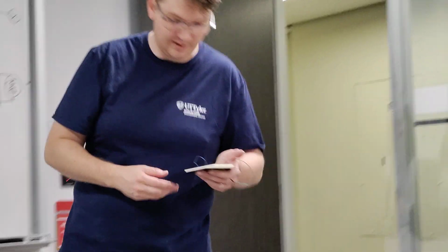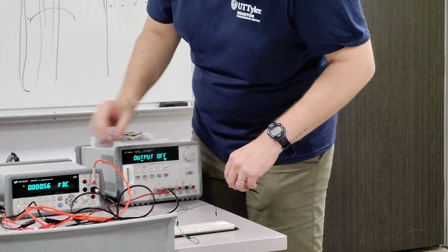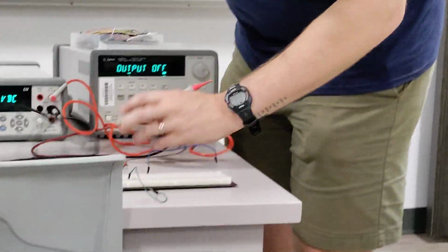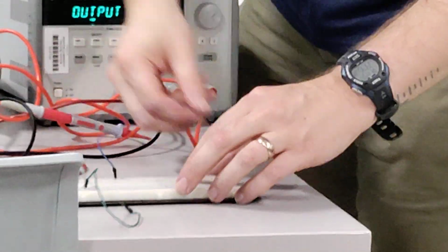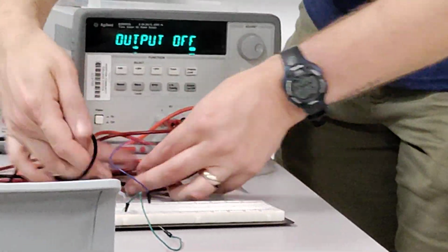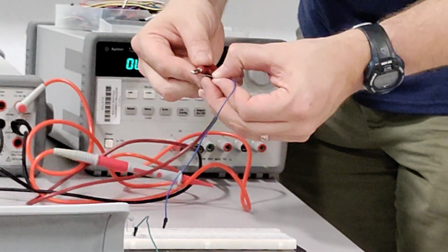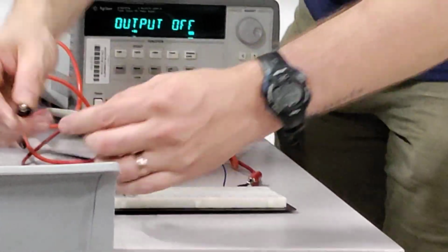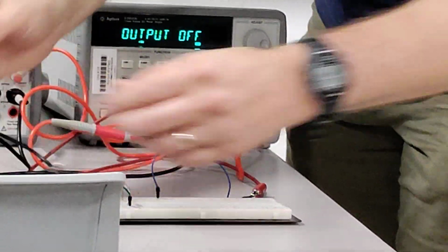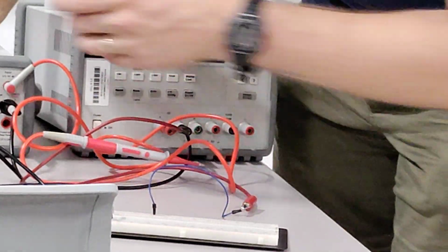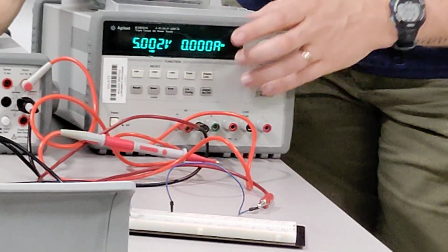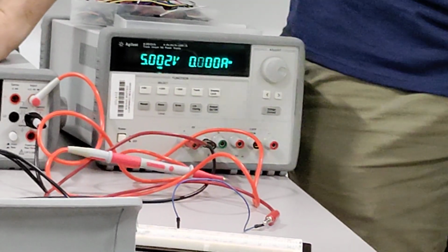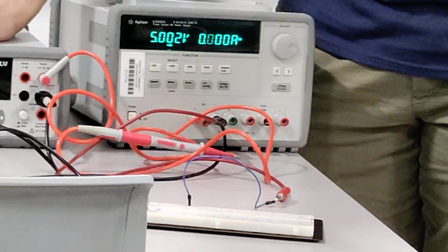So in real stuff land, I'm going to break the circuit, put this somewhere else. Let's call it the positive rail side. And I've still got my probes. And, all right, this is going to be my positive, coming off the power supply. This will be my negative. So I have the output on. It says 5 volts. It says 0 amps because the circuit is broken. It said 0 amps before, but because it was small. This time I know it's 0.